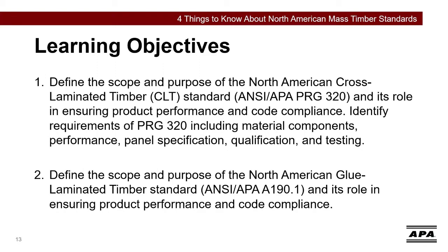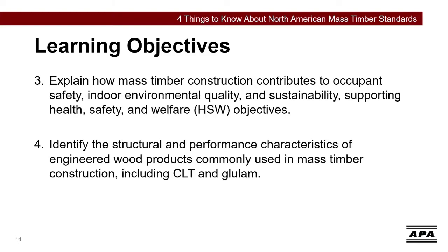I want to summarize the learning objectives for today's course. To understand the scope and requirements of the North American CLT standard, PRG 320, and to learn more about glue-laminated timber and its North American standard, A190.1. Finally, we want to identify the structural and architectural benefits of building with mass timber.